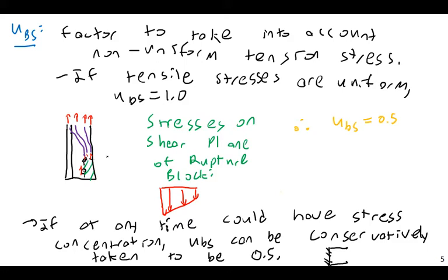One more question. Earlier you mentioned that the smaller the UBS, the more conservative it is. Did you say that means that the less tension it can handle? Yes, exactly. If you use a UBS of 1.0, you're saying this connection or this element can handle this much load in tension fracture. If you use a UBS of 0.5, you're effectively saying this element can withstand only half of my previous value. Okay, so I do have an example I think we have time to work through.